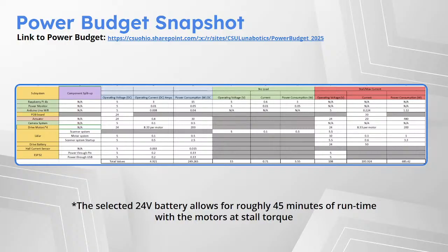By the motors? Yeah. I think he said like 2.3 Newton meters each. We've got four motors. And that's before you gear them down. So total, I think the total is upwards of 200 Newton meters of torque. Yeah, it's a lot. Gearboxes.